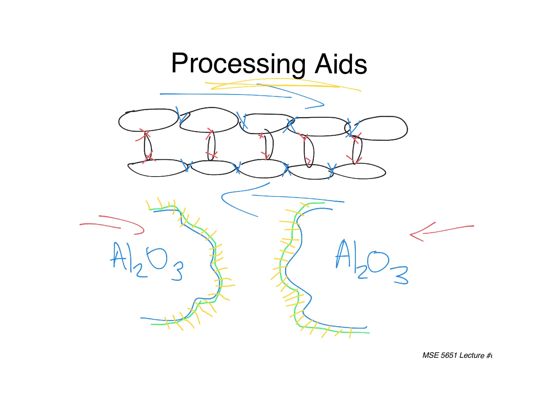Okay? And these are very important in that it keeps these guys from approaching too closely to each other and falling into that energy well and getting stuck. All right. And so we've talked about agglomeration. You guys have an idea what that is. It is something that is inevitable, as you can see from these structures here. You always have some type of agglomeration forming, but in the context of these polymer melts, there's a difference between what's called hard agglomeration and soft agglomeration.